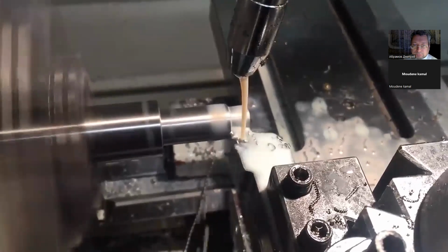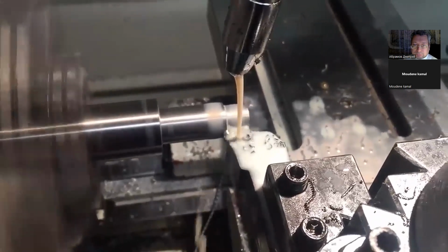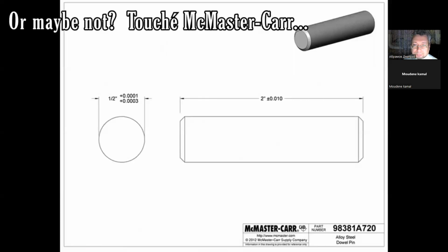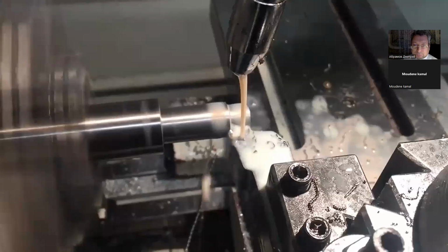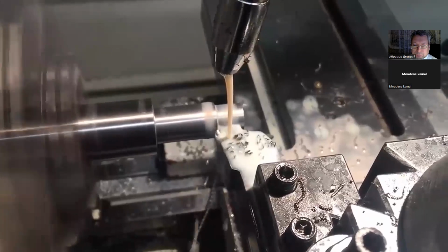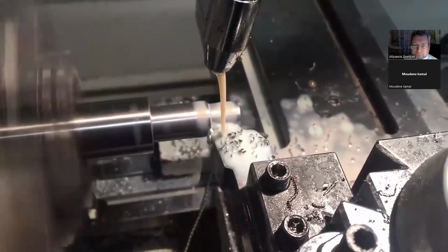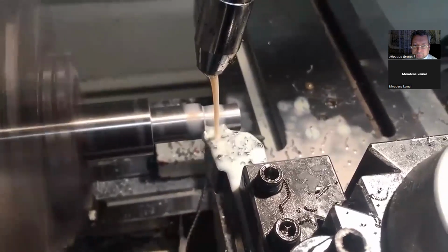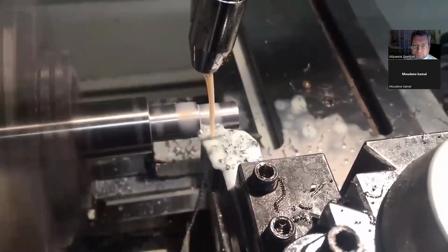You want to be able to tell customers what the tolerance zone is on each size of dowel pin, but it would be cumbersome to have to create engineering drawings for each size. So instead, you can just say that tolerance will always be a bit over the specified dimension, where a bit over scales roughly proportionally to the target size. We could say that all the pins will be between 0.1 and 0.3% larger than the nominal dimension. The problem is we don't want people to have to constantly calculate what these percentages are.